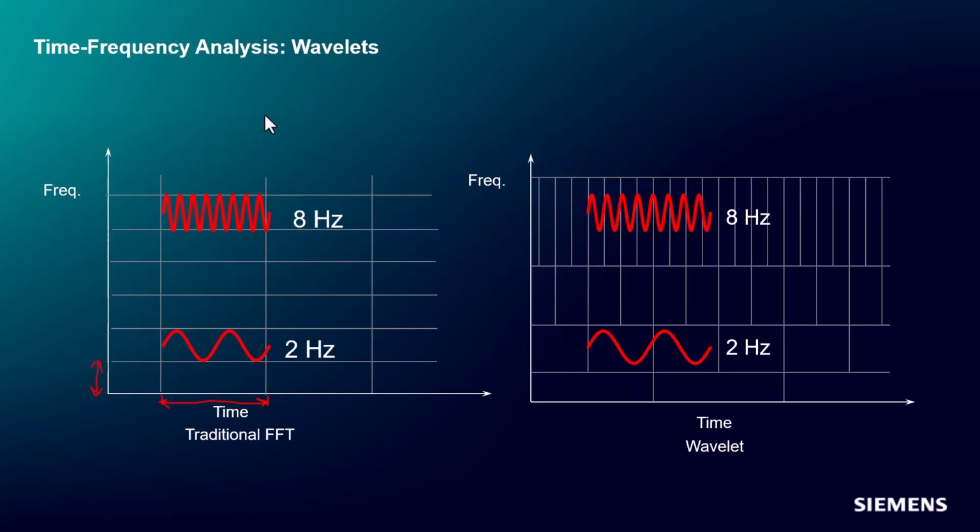And this just has to do with the fact that we're analyzing an FFT with a sine wave, which is at one frequency, and with a wavelet, which is at a couple different frequencies. So we get more of a trade-off. Now, once again, it's impossible to not have some drawbacks. So even though I can observe frequencies with a shorter amount of time at these higher frequencies, I still get a large amount of smearing.